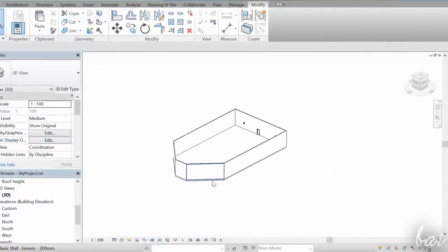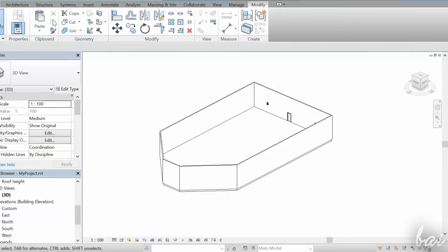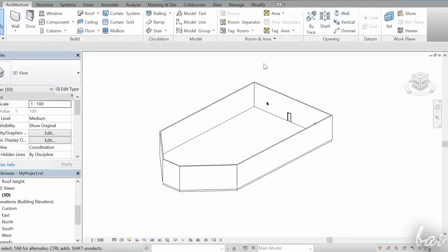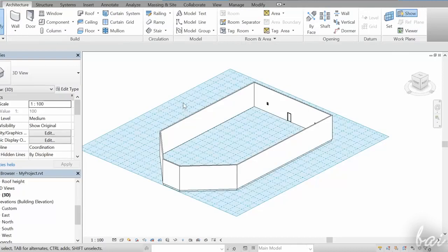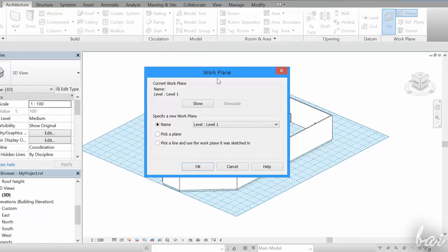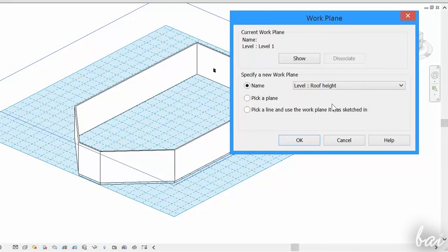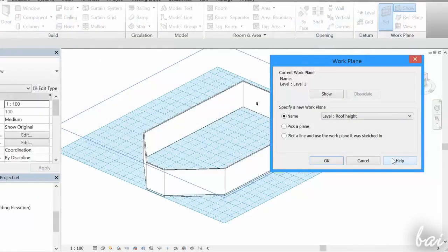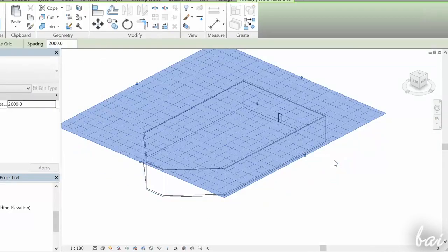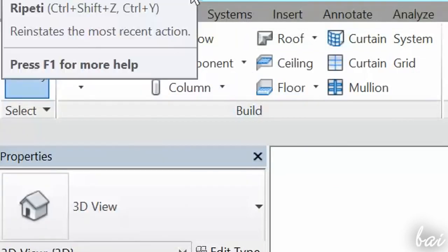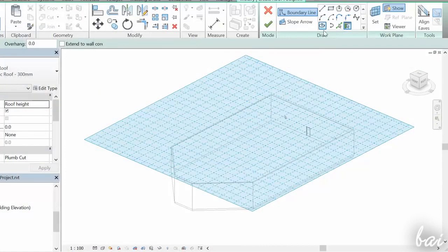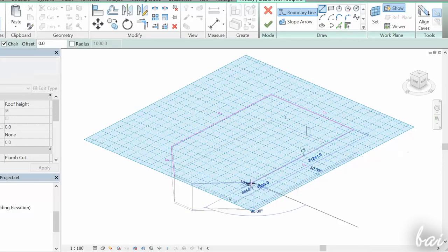To finish this simple house, we now need a roof. The roof object always lays to the current work plane fixed, which is the floor plan level used as reference. To fix it, go to Set under the Architecture tab and choose the right floor plan level to pick. If you click on Show, you can see the current work plane during a 3D preview. Then, just enable the Roof tool and choose the drawing mode as seen for the floors and walls. Click on your workspace to fix the boundaries of the roof, and these will lay on the work plane just fixed.